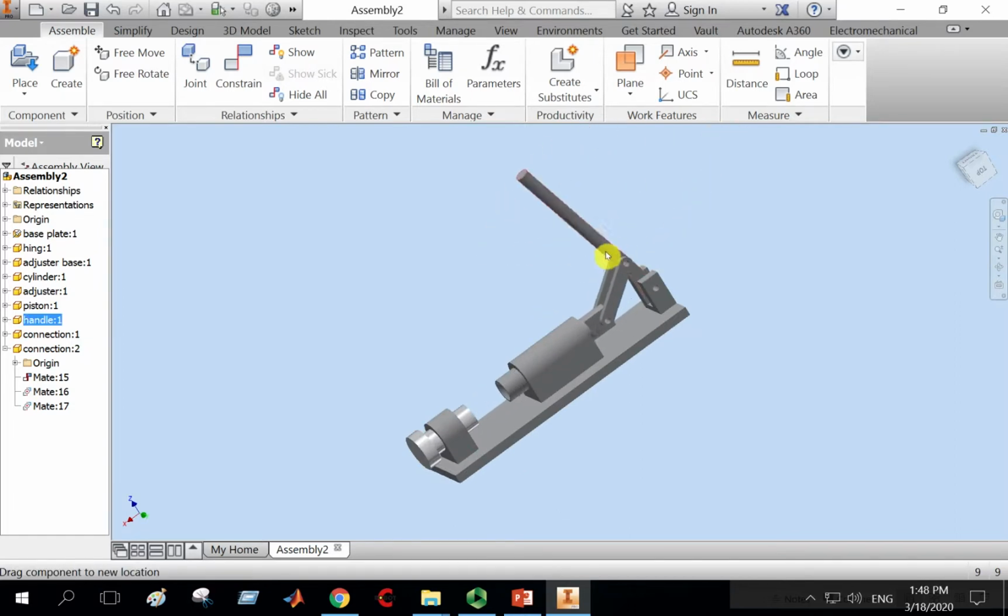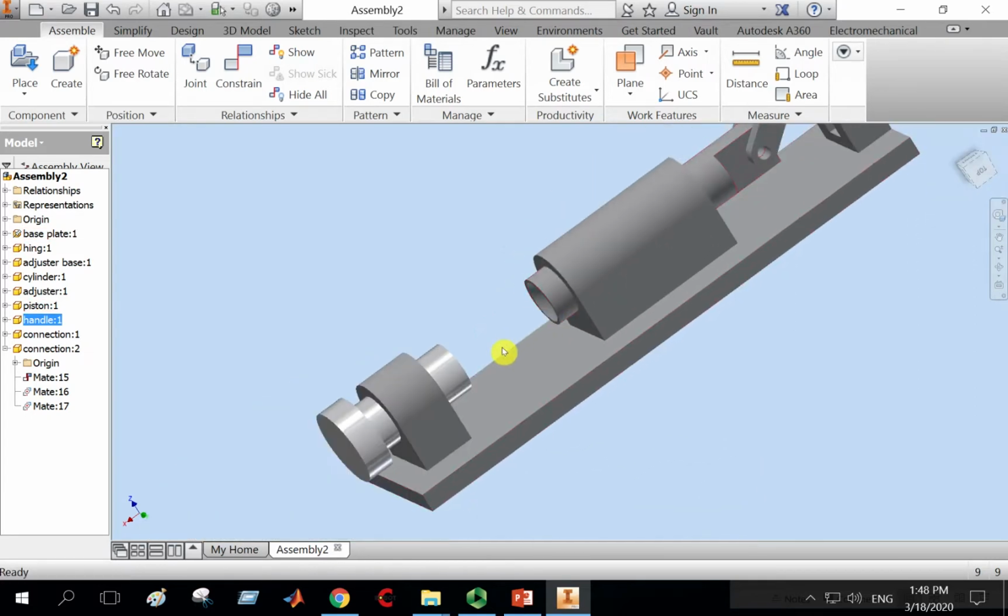Now the same story, guys. We want to drive the motion, we want to show just a demonstration. Now for the assembly, it's ready, no need to add more constraints. But if you want to show the motion, to drive the motion, we have to use one of the constraints. So let me add as example distance. We can add distance or angle.